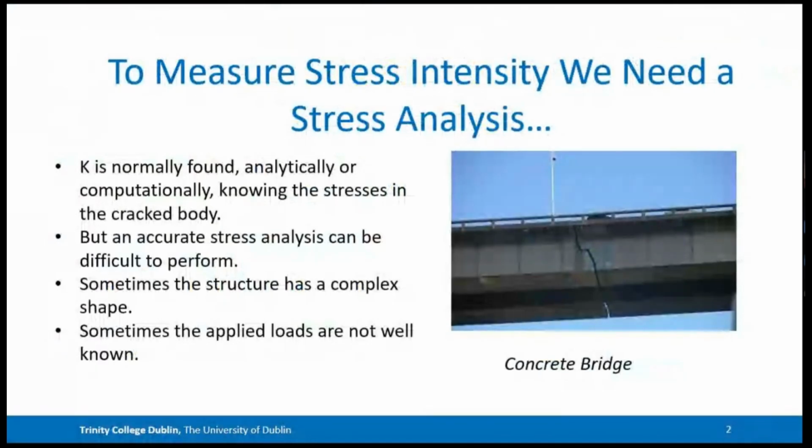Okay. So to measure stress intensity, everybody knows that you need a stress analysis, right? To find K, you normally find it either analytically with an equation, if the geometry is simple, or computationally with a finite element model or some kind of model, knowing the stresses in the cracked body. But of course, this is a very significant problem in practice, because in many cases, it's difficult to do an accurate stress analysis, because the structure is complex in geometry and loading, and sometimes you don't even know very well what are the applied loads that the structure is experiencing.